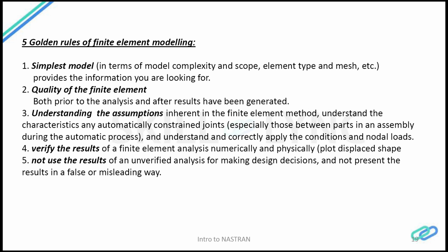For example, for a simple 2D panel kind of geometry, you can use 3D elements, but you are unnecessarily making the model complex, and then you don't have the proper justification once the analysis has been done.